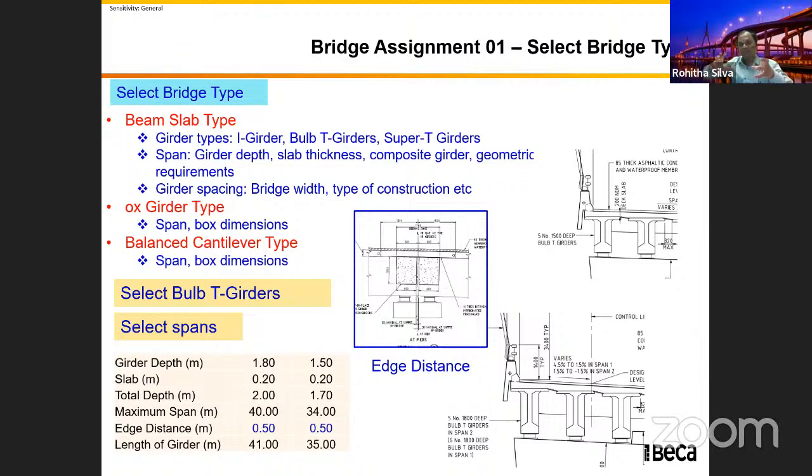I want to say, for example, in different countries, 1.8 may translate into 1.7, 1.5 may translate into 1.6 or 1.4, right? And then the girder is 1.8, then the slab is 200, because when you are building a bridge, we always use the slab and girder acting together like a composite unit.